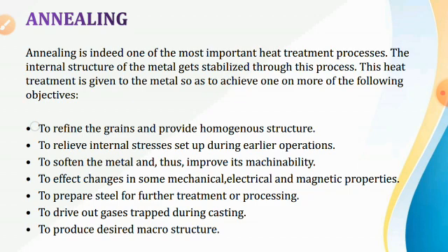The first one is annealing. Annealing is one of the most important heat treatment processes. The main objective of annealing is to reduce the hardness and increase the ductility. The internal structure of the metal gets stabilized through this process.